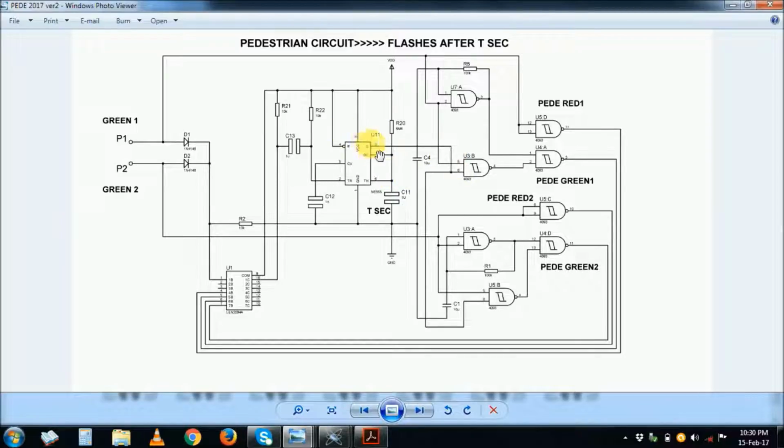So this timer will actually go high, and here we have a high, high is a low here, a low here is a high here. But this will actually go low after some time, some seconds. When this one goes low, it means you have a low there, and if this one is a low, it means this one is now a high. When this one is a high, it depends on this one now. But remember, this oscillator is running, and that one is off.